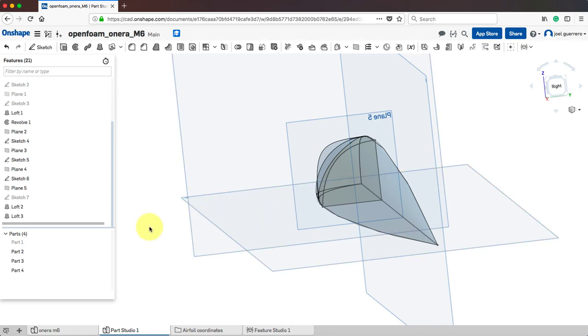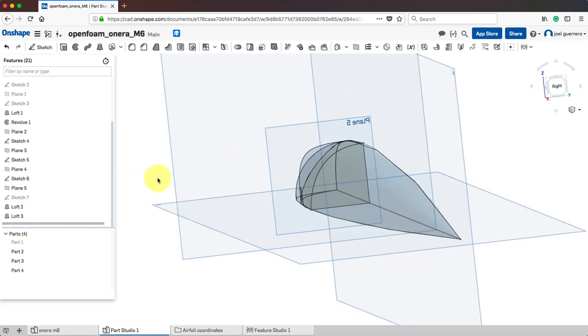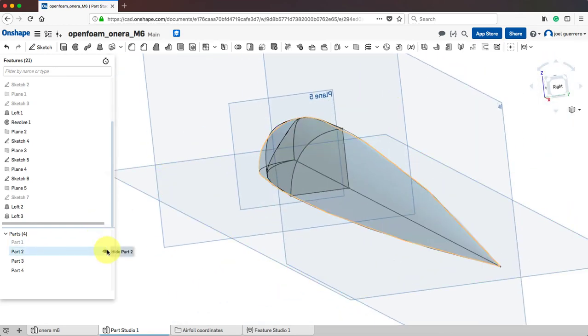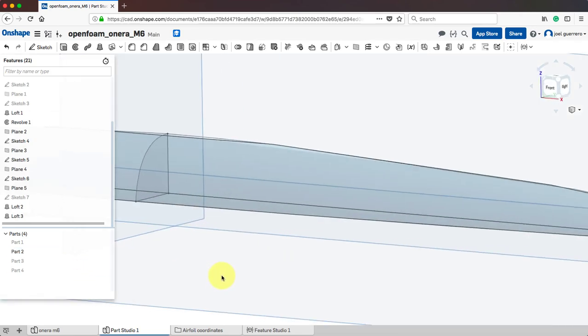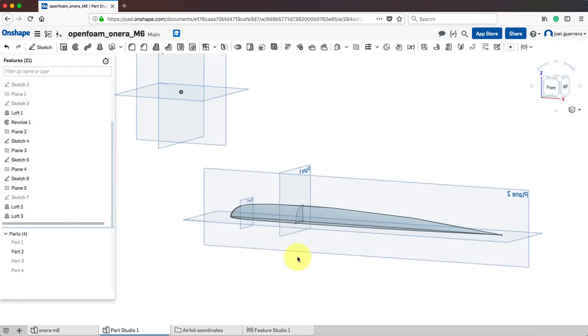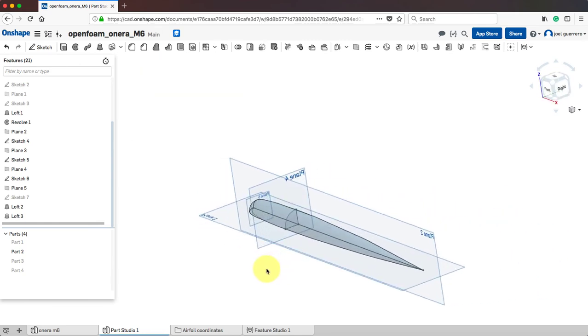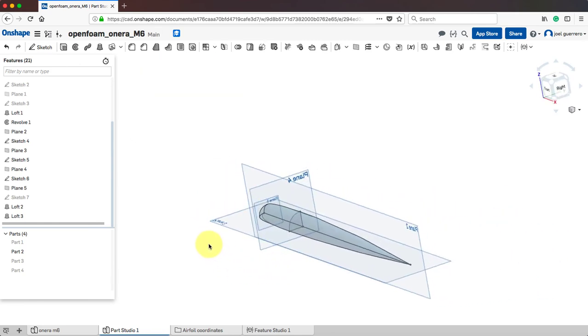So if you like this section in the revolve, that is a circular section, a perfect quarter of the circle, you can just create a cut plane, project that section there, and then do the lofting using that one. So let me show you how to do that. Okay, so in this case we have this one, and I would like to use that section of a profile.